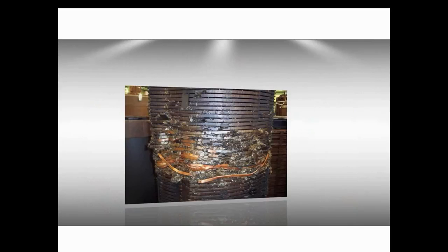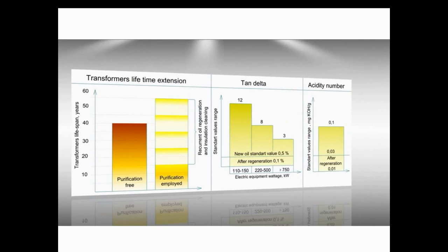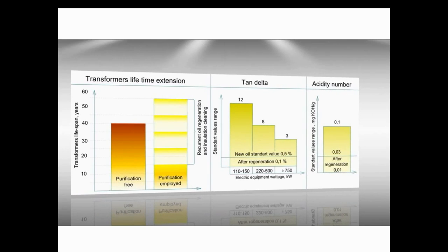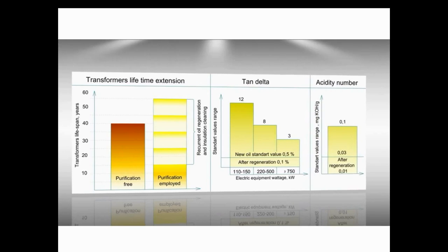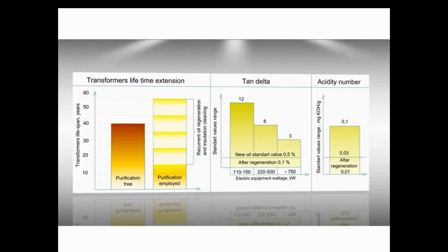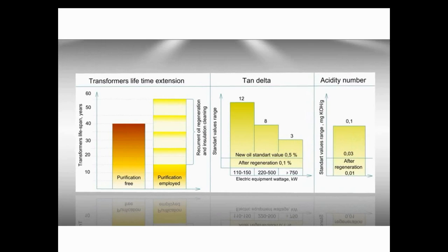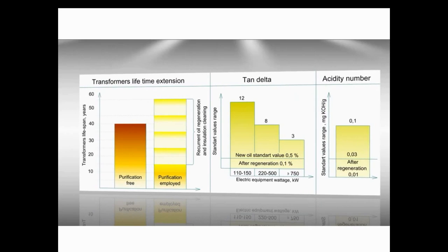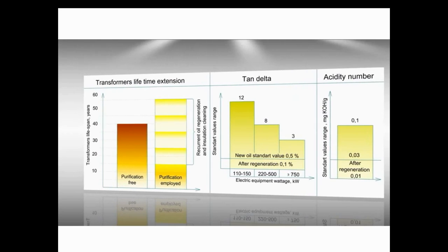And now we have come close to another core point. How can a regeneration plant help a transformer? First, when should we do regeneration? Every 10 years. Why? As we have discovered, oil oxidizes and decays. But if we can keep oil in good condition to protect paper insulation, we will expand transformer operating life. So it's a matter of logic to do regeneration early rather than wait for 25 years. Also, the DP value is still very good in 10 years, and oil hasn't yet become aggressive to the paper.